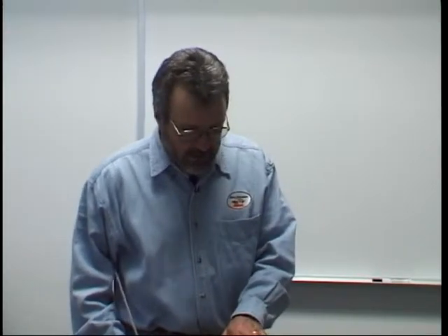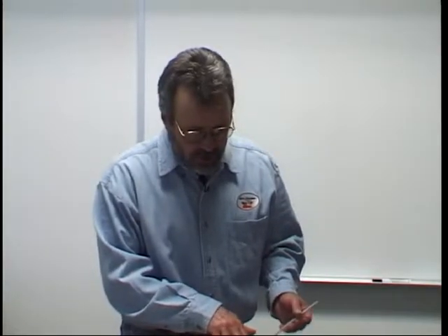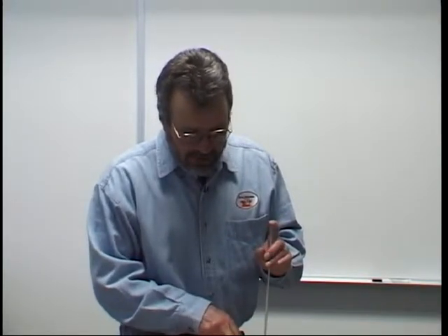Let's see, go ahead and flip the page to 750. In the first column it says, gas metal arc welding frequently replaces another joining process such as riveting, brazing, silver soldering, or resistance welding. Those processes are used, some are used greatly, and some are not so much anymore. If you read here, it also says it may be used instead of the following fusion welding processes: oxyacetylene welding, shielded metal arc welding, submerged arc welding, flux-cored arc welding, and gas tungsten arc welding. So you might use it in lieu of those other ones.